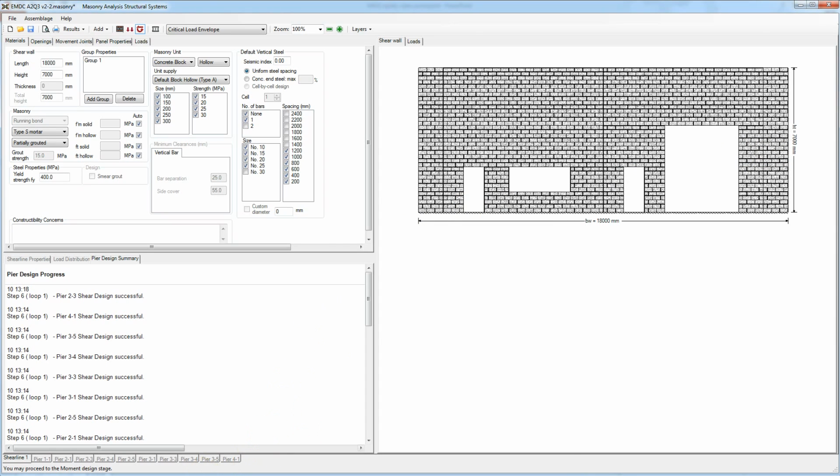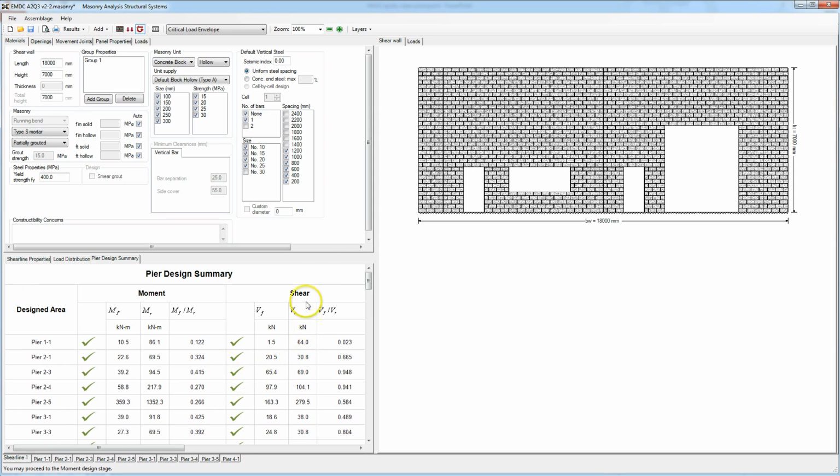You can see I selected quite a few piers on here. The more piers you select here, the longer this process will take. Same thing with your file size. When you save this, now we're saving something like 12 shear wall modules, and so the file is larger.